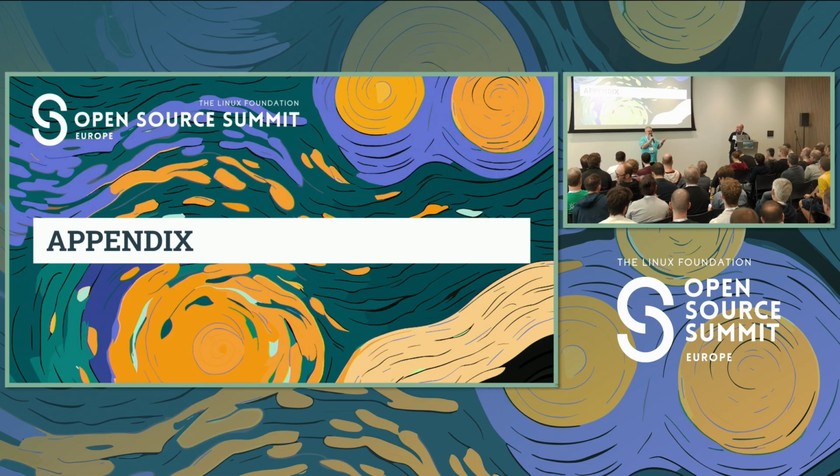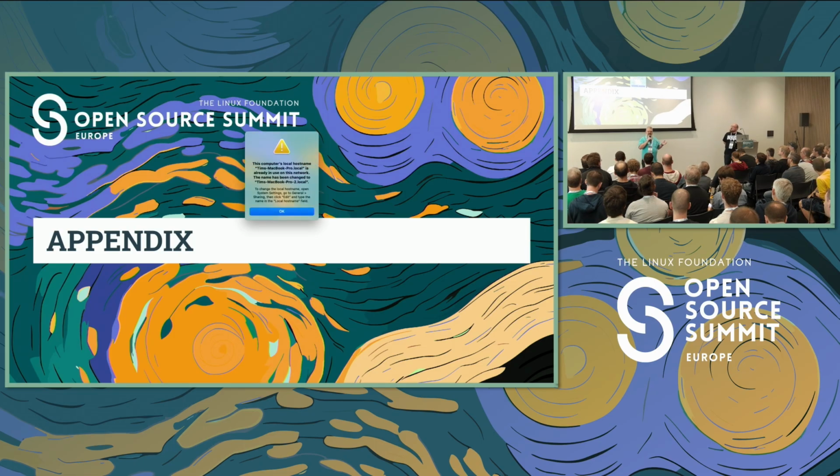So what I did for the BeaglePlay, from what was shipped to me, I just took a new installer image, used the Beagle Imager tool to put that installer image on an SD card, booted it, and flashed it to the eMMC. After that, I'm not touching that image anymore. But I use Ansible to upgrade the Debian image, right? So there's other things I've got, like Ansible. Lovely.